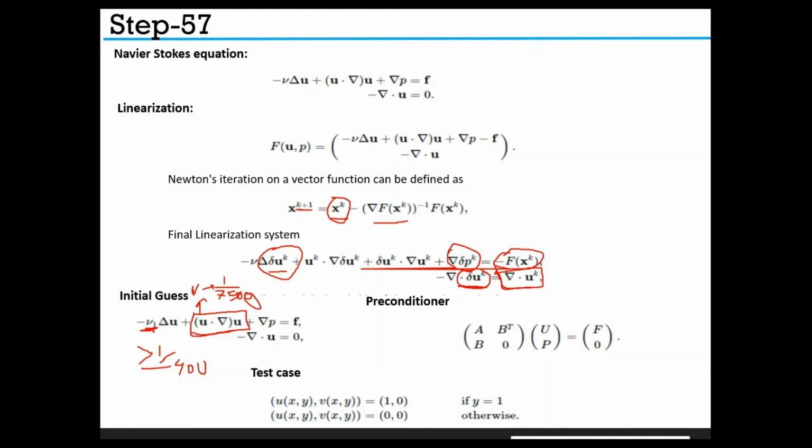So in this situation we use the continuation method to set up a series of auxiliary Navier Stokes problems with viscosity approaching the target Navier Stokes viscosity. So though the initial guesses are something different, the final guess would be like that. In this process, the sequence of viscosities vi is determined experimentally, so that the final solution can be used as a starting guess of Newton iteration.